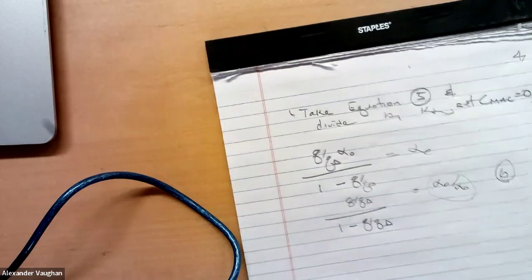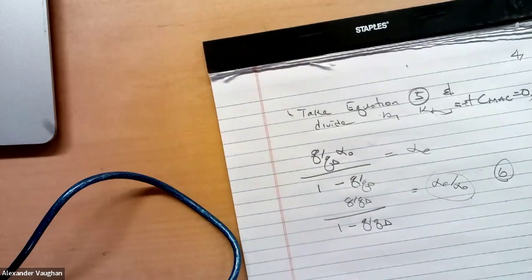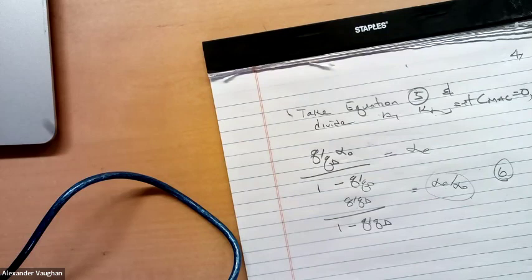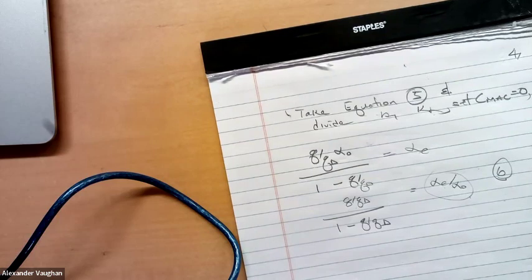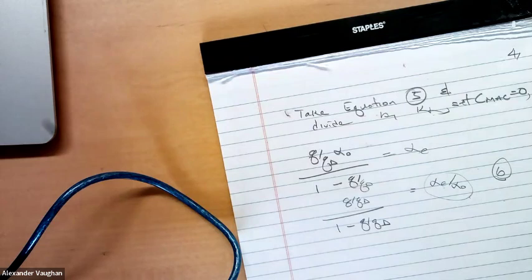Another thing you can do is look at the lift, how much lift I have on my airfoil now that I've allowed it to have an elastic twist. The lift has actually gone up. In fact, the lift also goes to infinity at Q divergence. Well, you want more lift, but you probably don't want that much, right? But it is true that in modern aircraft, we take advantage of the fact that the lift for the deformed wings is more than for the undeformed wing. And you can do that provided you don't get too close to divergence.